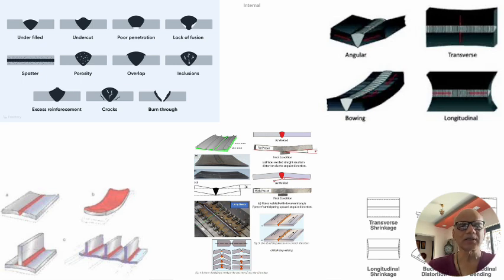The last defect, that is the burn through, is mainly because of the defect which occurs when you use excessive current, larger gap, lower thicknesses, and improper welding speeds. So there are many reasons for burn through, and if you are not having a good control over your welding, the burn throughs are unavoidable, and once you have a burn through, you really make a larger root gap in that area, and then to fill it up is a real trick.